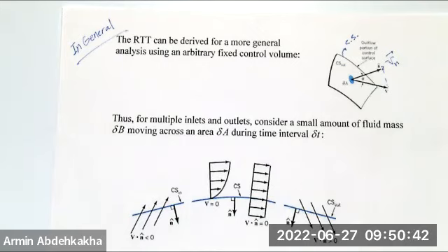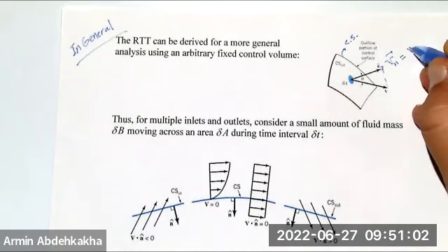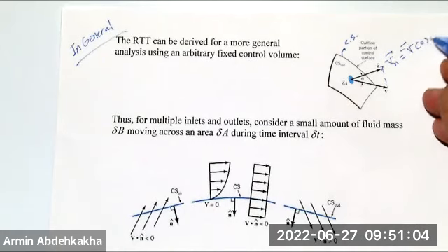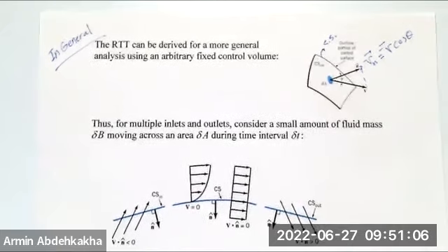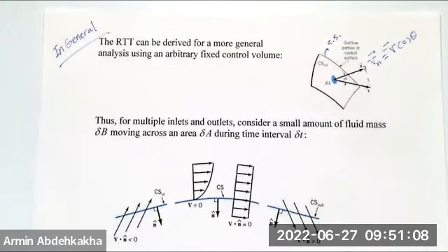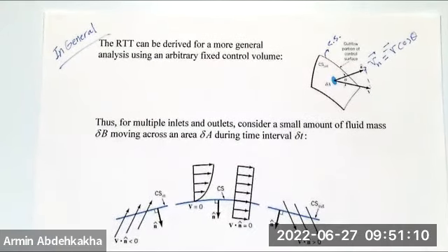It's not hard, because you can find the angle and the velocity of the wind, and you know the normal direction is normal to the area, and you find the component of velocity by multiplying by the cosine of the angle, right? So Vn is, from mathematics, velocity times cosine of that. Okay.